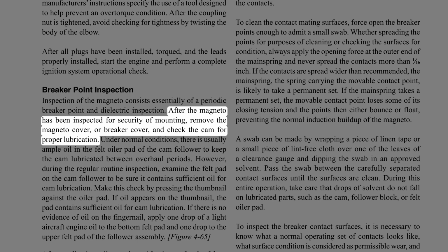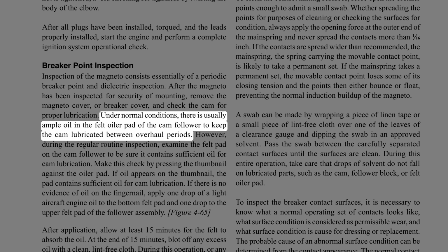After the magneto has been inspected for security of mounting, remove the magneto cover, or breaker cover, and check the cam for proper lubrication. Under normal conditions, there is usually ample oil in the felt oiler pad of the cam follower to keep the cam lubricated between overhaul periods.